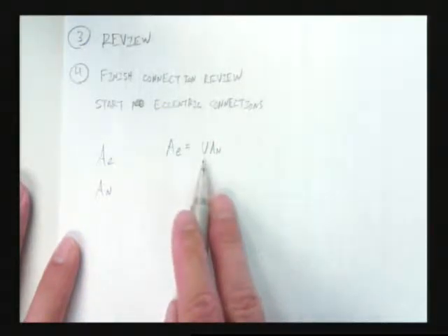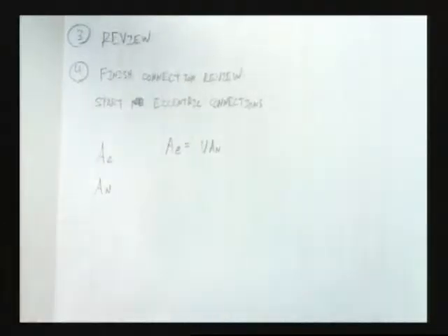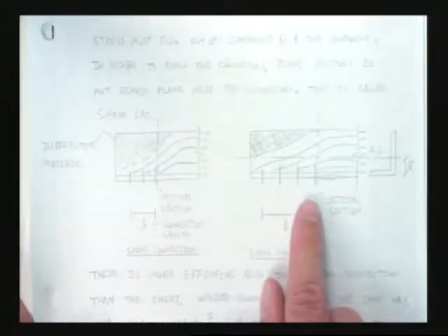And what is U? What does it do? It accounts for shear lag. It accounts for the area that's not transferred into the other members of the bolts. Yes, it accounts for the area that has lower amounts of stress in it. It accounts for a non-uniform stress distribution, right? We use this: 1 minus x bar over L.